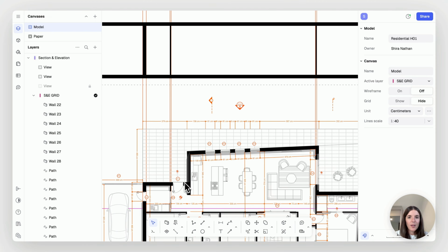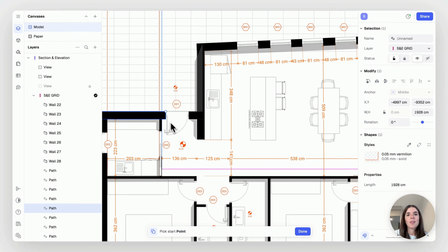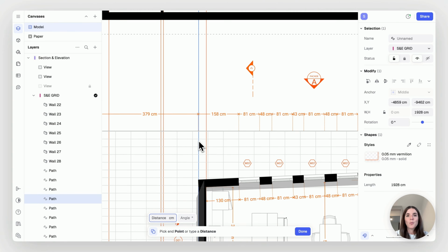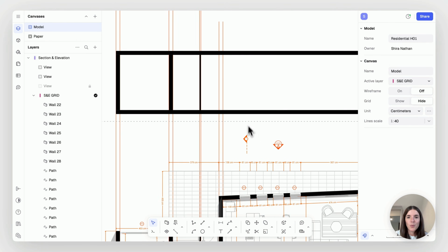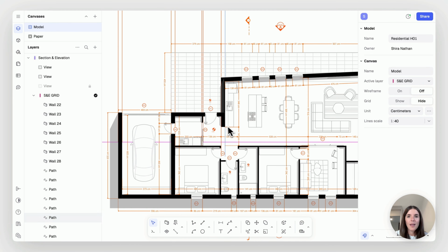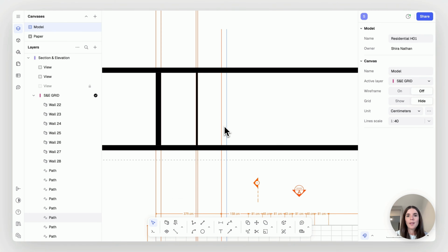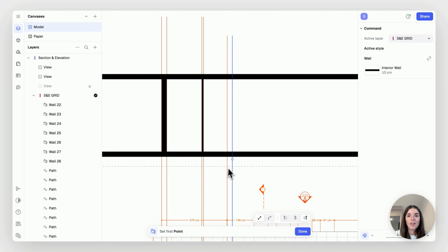There's also this wall here that isn't cut. So when you're creating sections and elevations, the thickness of the lines and the color of them represent what's cut or not cut, meaning in view mode. So you see, we cut through these walls, but actually here we're looking at the tip of a wall which isn't cut, which means we can probably indicate having this wall, but with a brighter color to make sure that it's readable.